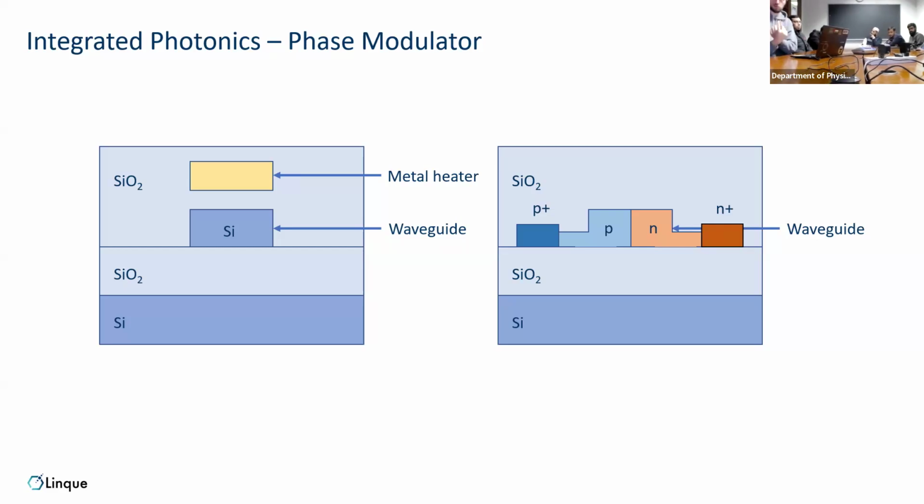So this effect is very small, right? These phase shifters, if you want a high phase shift, which means full range until basically the waves overlap again, can be hundreds of microns or even millimeters in length. If you build it, for example, as a transmitter for optical signals, you can have one chip of this size, and the whole length is the phase shifter.